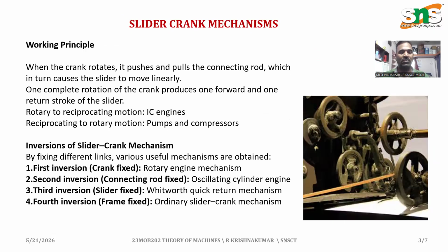Before going to see the working principle: the working of the slider crank mechanism is simple and highly effective. When the crank rotates continuously, the connecting rod transmits motion to the slider, causing it to reciprocate in a straight line. Similarly, if the slider is forced to move back and forth, the crank rotates. This motion conversion capability makes the mechanism highly useful in practical engineering applications.